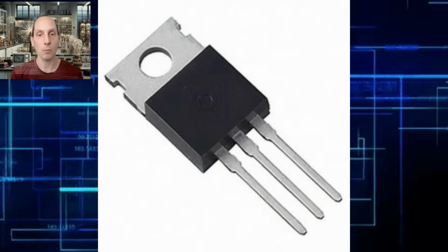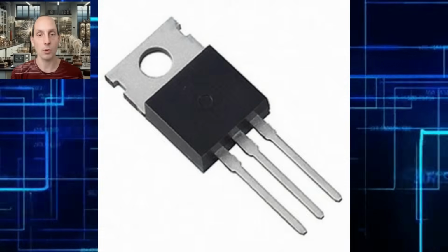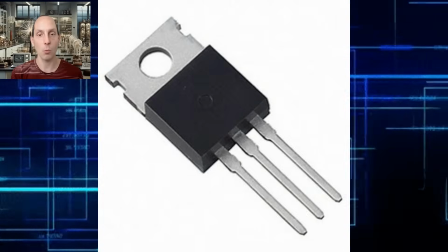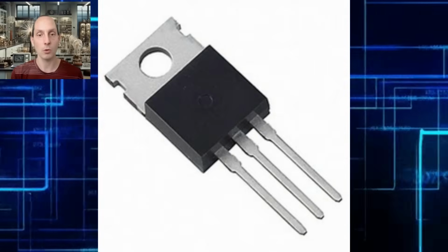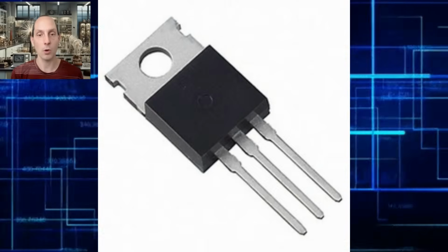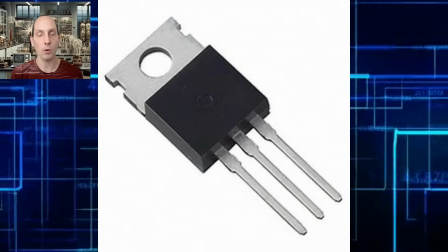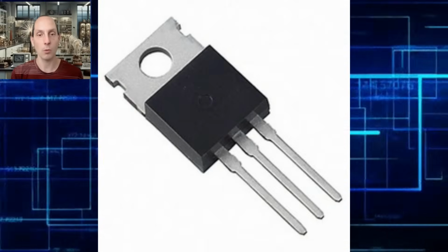In a standard NPN transistor, e.g. 2N2222A, the base-emitter junction behaves like a forward-biased diode requiring about 0.6 V. The base current modulates collector-emitter conduction. The device acts as a current amplifier, not a field gate. Such behavior is conduction-dominant, responsive primarily to charge carrier movement, not to field variations.